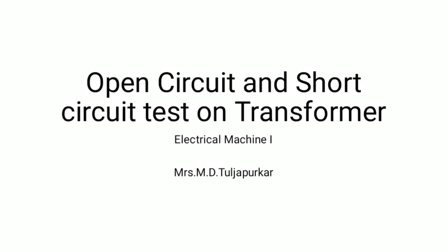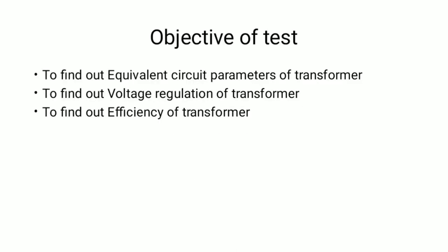Hello all. Today we will see open circuit and short circuit test on the transformer. The objective to perform this test on the transformer is to find out the equivalent circuit parameters of the transformer, to find out voltage regulation of transformer, and to find out efficiency of the transformer.